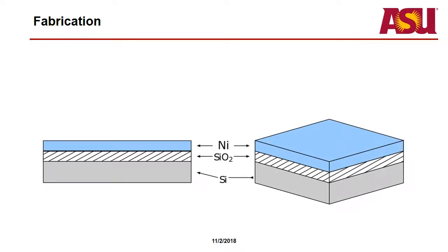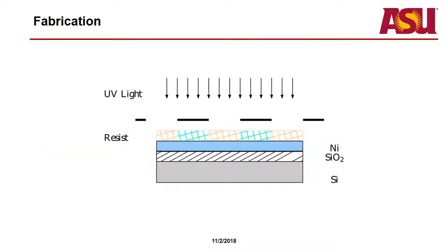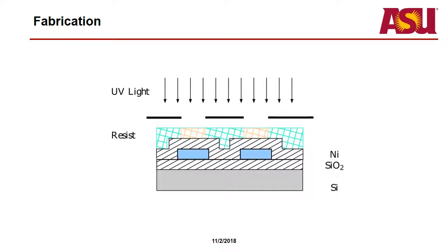Next, we do e-beam evaporation of nickel to about 65 nanometers, and then we will pattern that using contact lithography and wet etch that to get the cathode bars. So that's these going into the screen here. And then next we'll deposit more SiO2 to create an isolation between the devices.